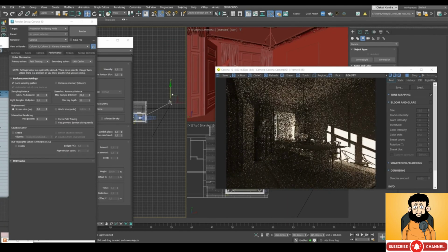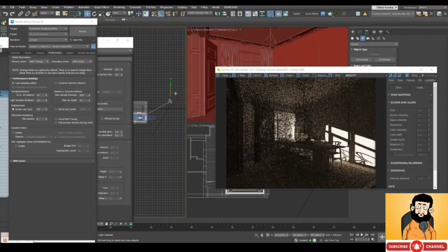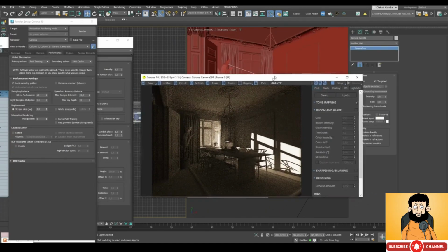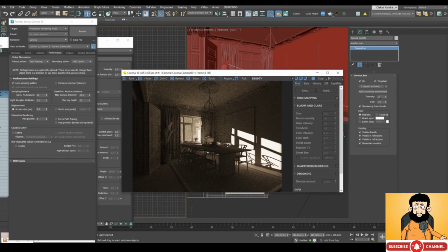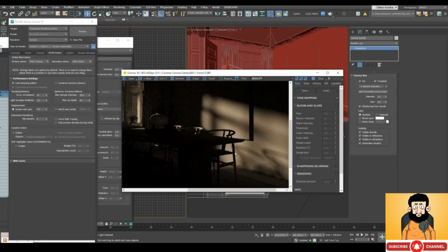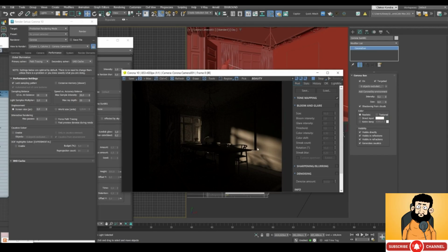The only thing I'd like to fix is the sunlight thing. Right now it looks very bright and sharp. So I'm gonna lower and soften it up a bit. Let's set intensity value to 0.1. And now we're gonna increase the size value. Let's make it 8, for example. You can see now that the shadows are softer, and that looks cool.